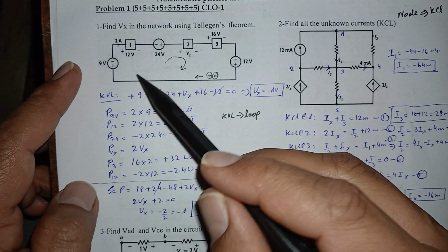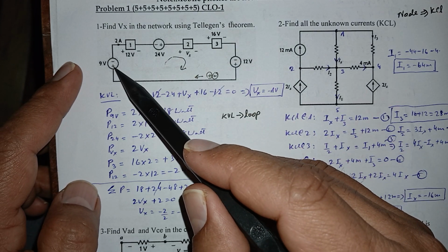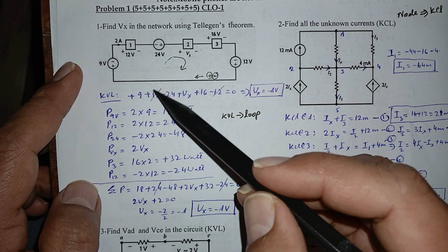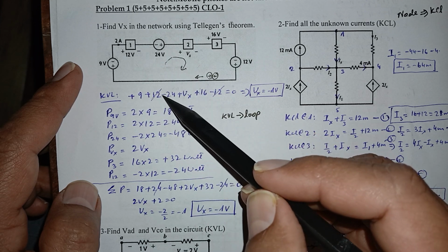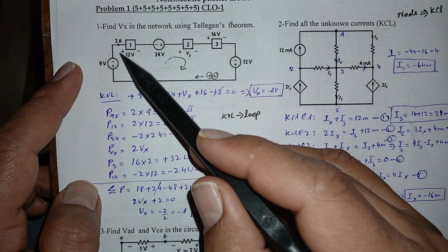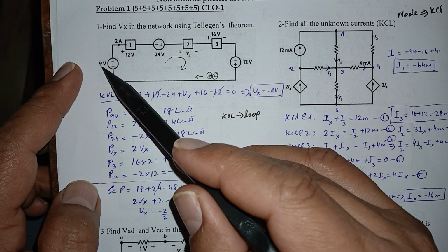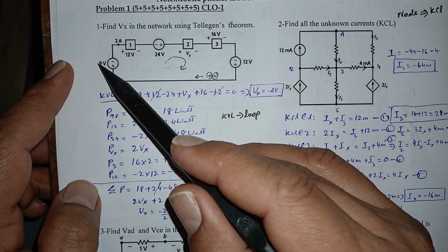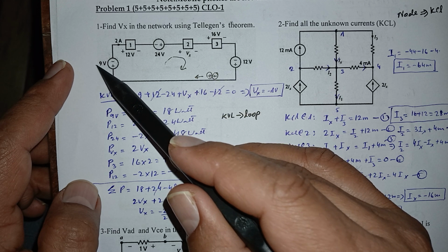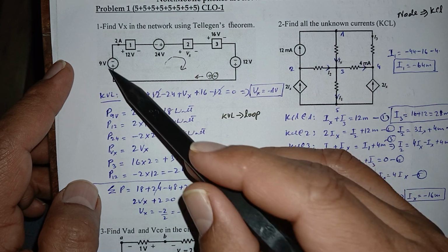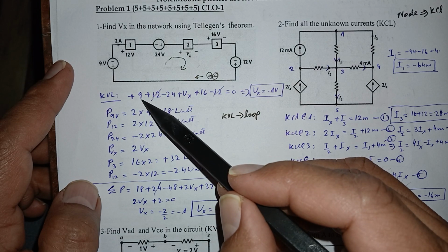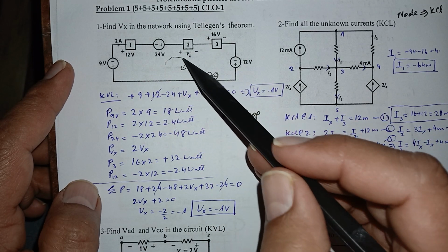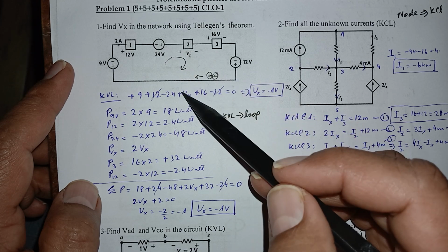You'll just assign a variable. So if you hit a positive terminal of the polarity, then that comes here. If you hit a negative terminal, that negative comes here. Regardless of the sign of this voltage, this can be minus, this can be plus, whichever the sign is, you will just copy as it is over here. So this was plus 9, I copy plus 9 over here. So plus Vx, the charge is coming and hitting a positive terminal, so I'll write positive.